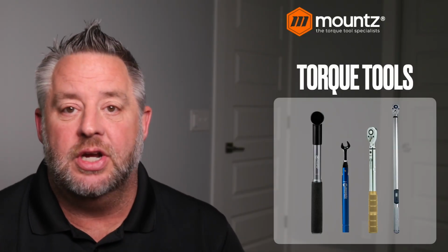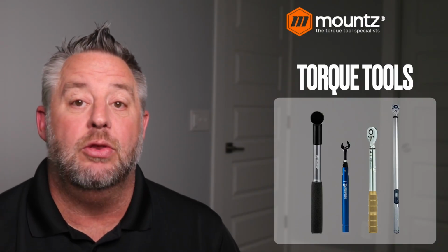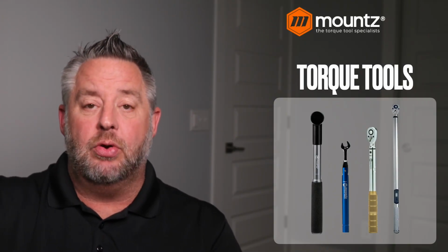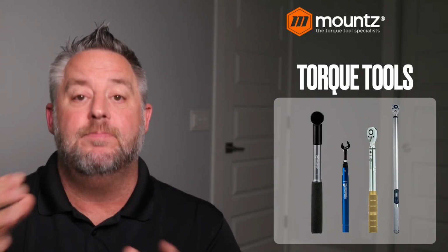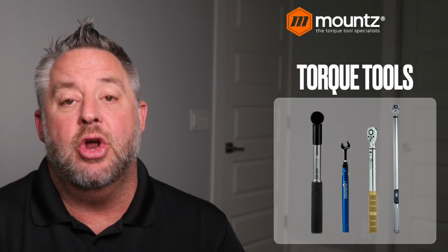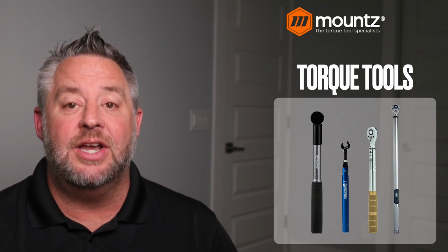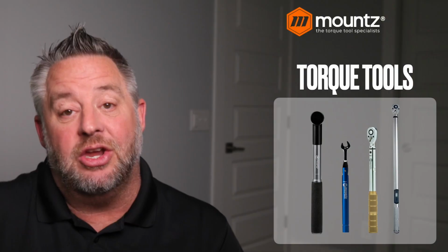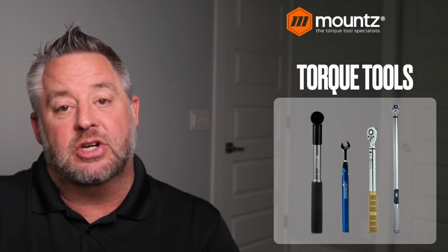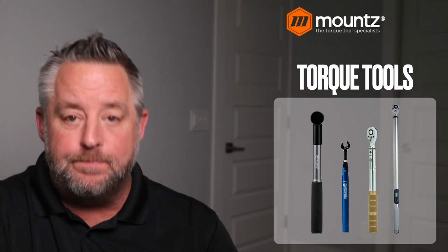The click wrench, which is by far the most popular and most used wrench in the world. As we pull that wrench, it will click. It will give you a little bit of a movement to notify you that torque has been achieved. However, it does not guarantee that you're not going to add additional torque, because once the wrench clicks, if you keep pulling on it, you're adding additional torque to the assembly.